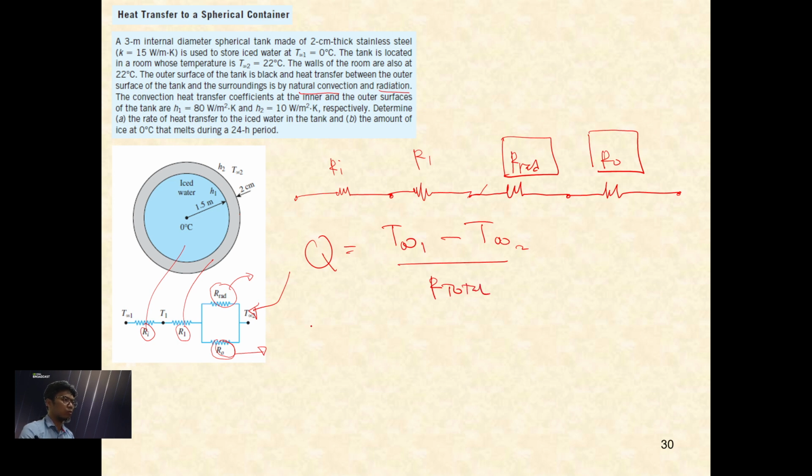So R total equals R convection of inner plus R conduction for the spherical tank, we put it as R1, plus R for this, which is R equivalent.